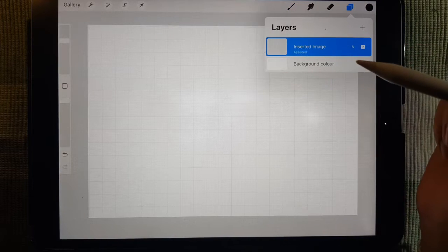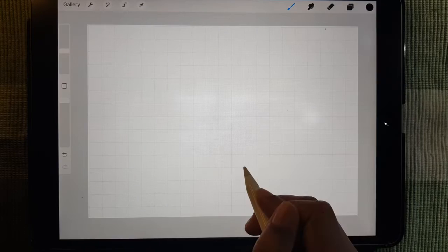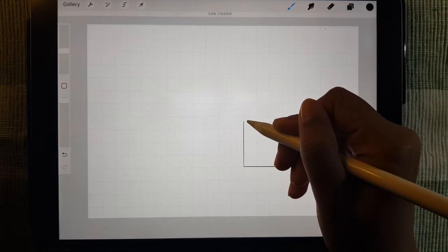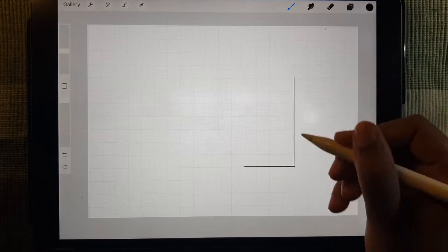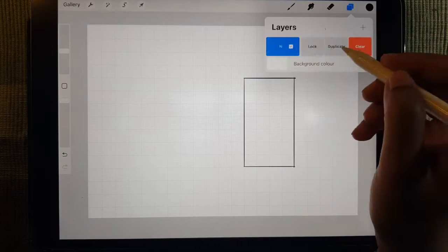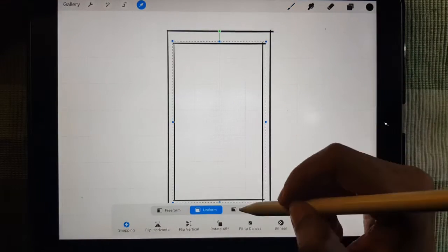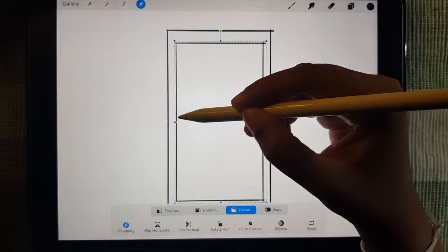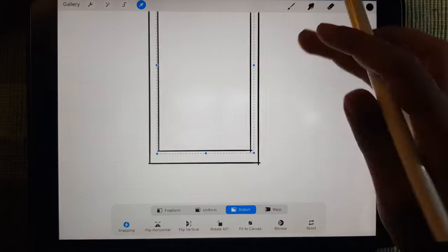Make sure to have your drawing assist option on your layer, and you can have a reference image, or a plan that you have already drawn, and keeping that in mind, you can draw your elevation, because in the plan you will know which room is what dimension, and with respect to that you can count the number of grids.